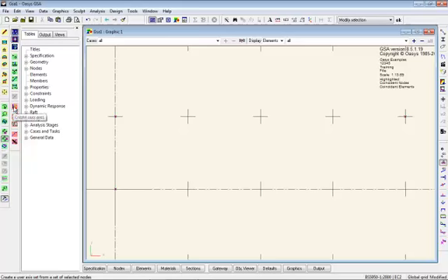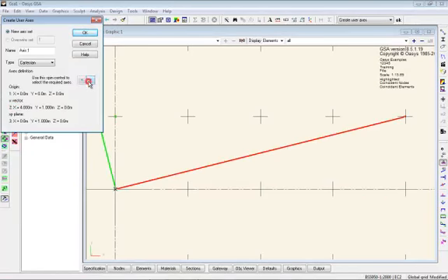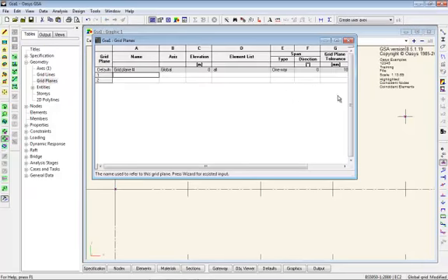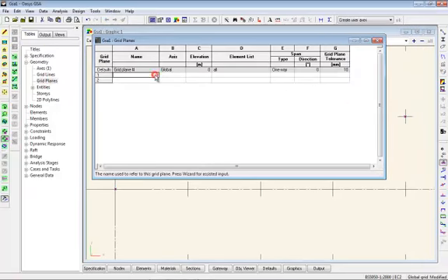And we use this create user axis, and you can see the red, green and blue arrows which show the various different options on the axis, and this one I want, which is the x-axis going up that 1 in 4 slope. I'm going to call this axis deck. I mentioned that I now need a grid plane which is defined by this axis. So a grid plane which I'm also going to call deck, and the axis is deck, the elevation is at 0. Elements list is going to be all.